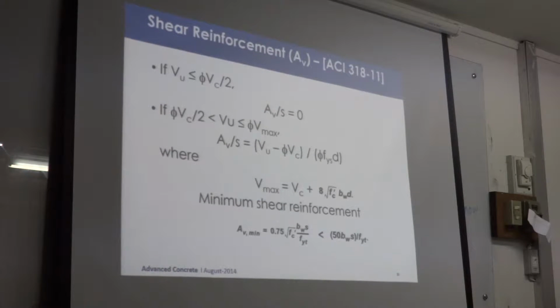Brittle failure may occur, because of all the other failures that are possible. Aggregate interlock may be lost because even if the concrete is gone in tension, if you put a lot of shear in that, there is also compression failure that can come in concrete, right? There is aggregate interlock that can happen, which the rebars will not be able to sustain. So basically, the beam can be completely disintegrated so much that reinforcement is not even locked anywhere. There is no concrete left to lock the bars, right? Everything is broken so badly that there is nothing left to hold the rebars together to take the shear.